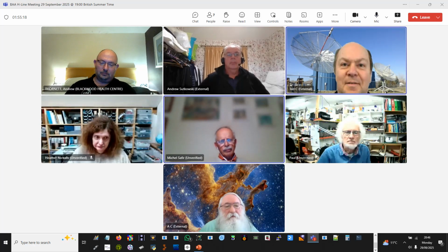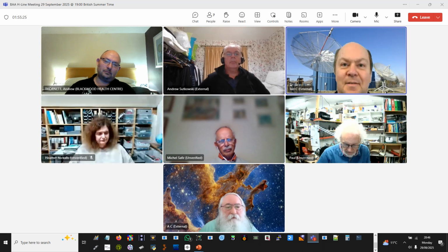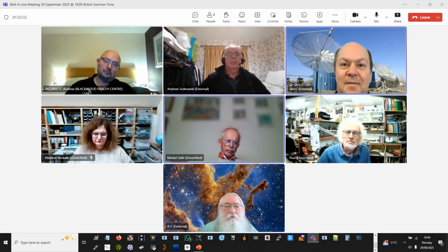I found that interaction, I don't know, two years ago now, I think. I was pointing them at the sun and just showing that I was getting interference. I was making a very cheap interferometer, but it's an adding interferometer because I'm just shorting the cables hot to hot and cold to cold together. That way I could power the LNAs right next to the antenna feeds, that was handy for me. That's all in a video if you really care.